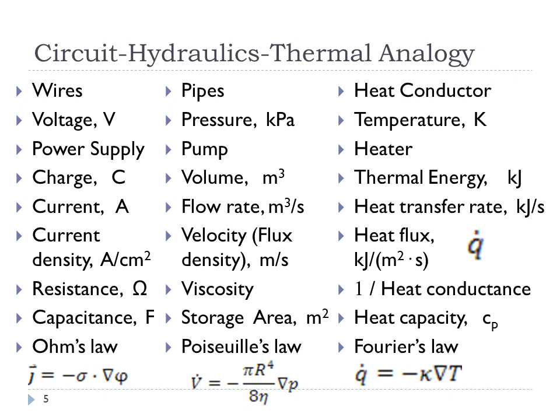Then you have something called a flow rate, which is the volumetric flow of gas or liquid. And here, velocity is basically the flux density. As you saw in the other one, current density was amps per centimeter squared. Here, we're taking meters cubed per second and dividing by the cross-sectional area of the pipe, and what you'll get is some kind of velocity.